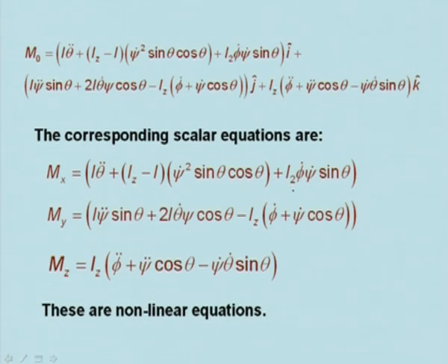The corresponding scalar equations are Mx is equal to I theta double dot plus Iz minus I psi dot square sin theta cos theta plus Iz phi dot psi dot sin theta, and My will be I psi double dot sin theta plus 2I theta dot psi dot cos theta minus Iz phi dot plus psi dot cos theta theta dot, and Mz will be Iz phi dot plus psi dot cos theta minus psi dot theta dot sin theta.